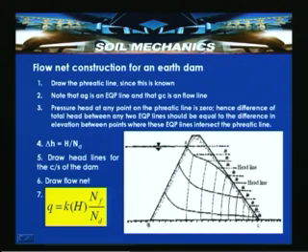There are some deviations here where the orthogonality is again not maintained. So, draw the phreatic line. This is known. Note that AG is an equipotential line and GC is a flow line. Pressure head at any point on the phreatic surface.